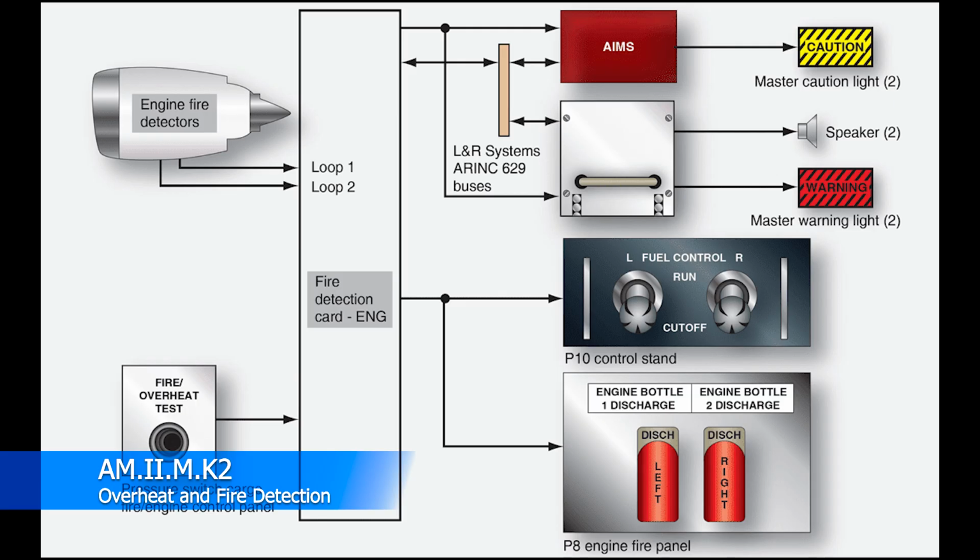Both systems have to indicate a fire for it to actually give you a fire warning. If not, it's going to assume that there's something wrong with one of the two loops. What ends up happening is that it leverages AND logic. You remember from our digital logic class that you have to have both conditions met for a certain